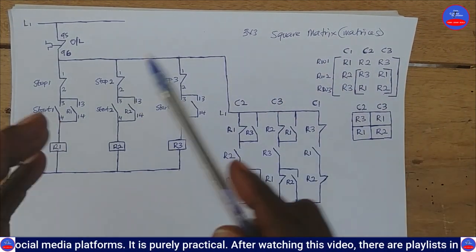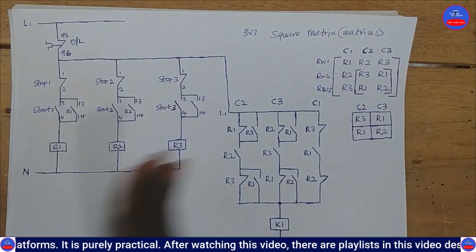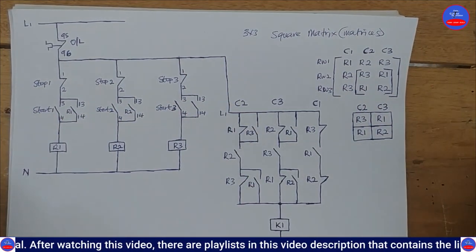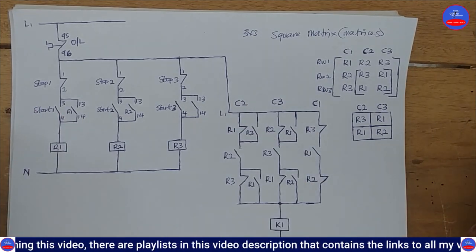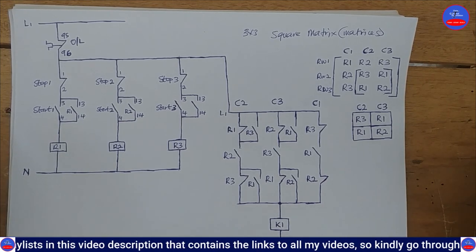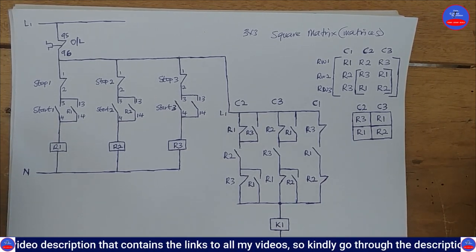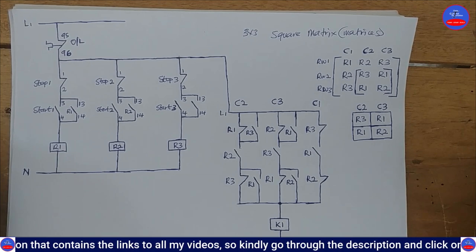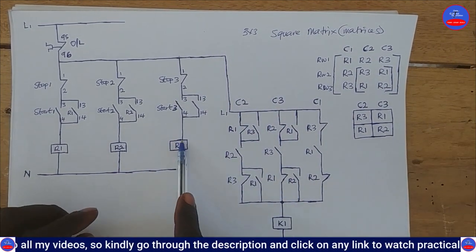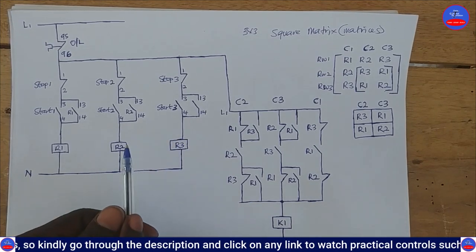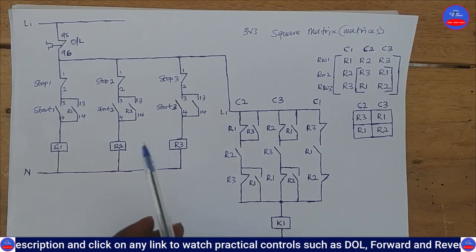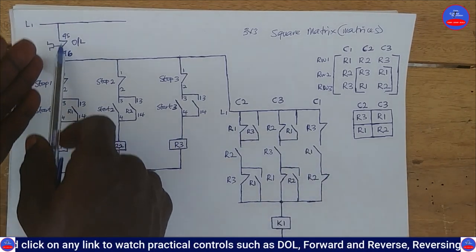So now we are going to stop the motor using any of the 3 switches. We are going to de-energize it. Which one should you press? You can press any. So I'll choose stop 1. Let me choose stop 1, because I came all the way to start 3 to energize the contactor again. So let me stop it using the stop 1.